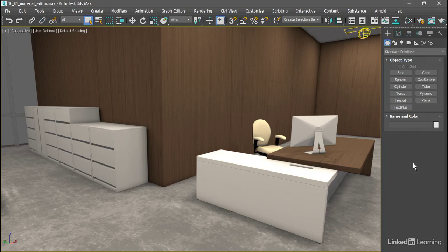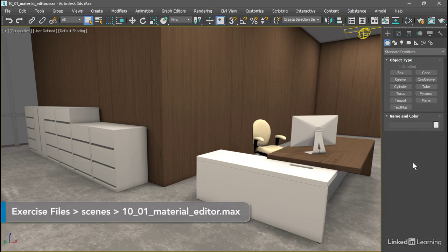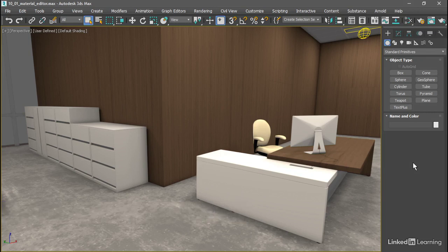The Slate Material Editor is a node-based interface for designing and editing shading networks, or material shader trees. Before you open up the Material Editor, you should know that by default it depends on the active production renderer. The production renderer will be invoked by the Material Editor in order to render previews or sample swatches. Also, materials and maps that are not marked as compatible with the current production renderer will be hidden within the Material Editor. So let's investigate.